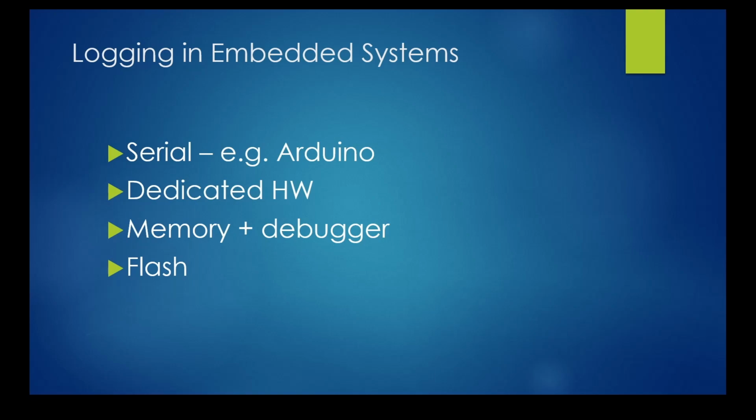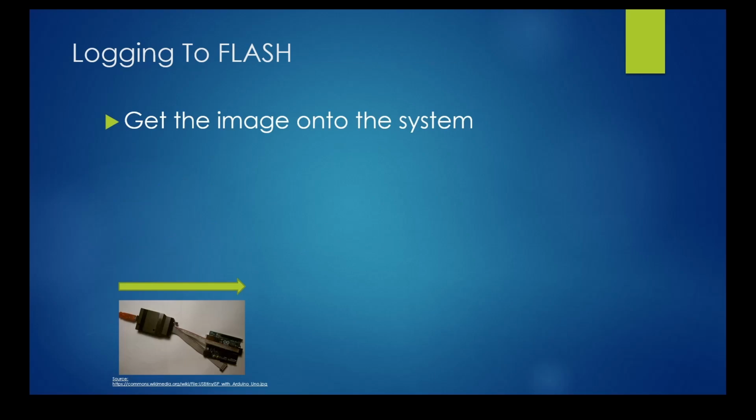This is generally a good idea to do some logging to flash regularly, since flash survives system resets and power losses. However, too much flash logging can shorten the life of the flash device. Logging to flash will look like this.